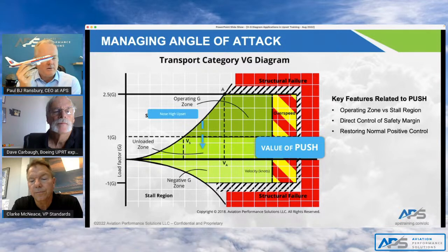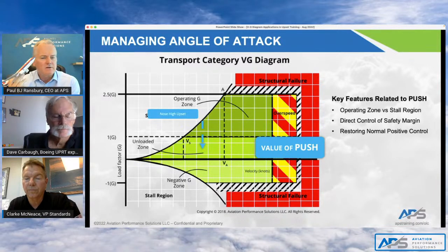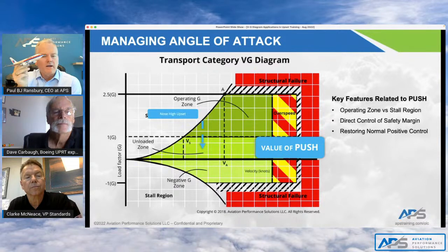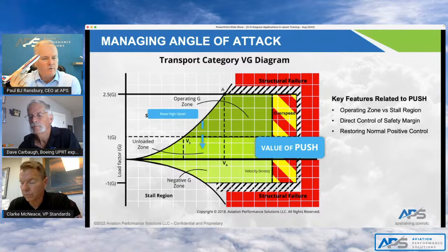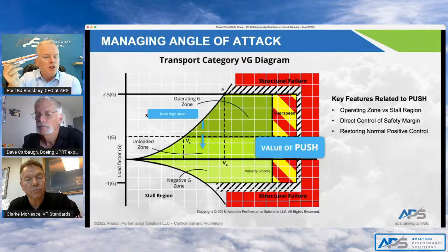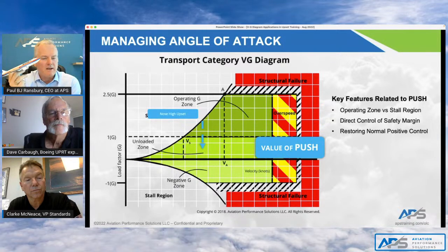Depending on the airplane and the technique recommended by the OEM, it may be a complete straight wings level push, or in certain situations, you may have to unload all the way full forward and then actually roll the airplane to help roll that lift vector off to get the nose coming down. It's not uncommon in these scenarios, especially anything 30 or 40 degrees nose up, to be over the top below the 1G stall speed, but there's no reason for the pilot not to be in full control. They have to push and unload below 1G, which is a great example of why, in your mind as a pilot in an upset, including a nose high unstalled upset, the focus is managing angle of attack. Even though you're not stalled, you're mitigating the threat, which is the upcoming stall if you don't manage angle of attack effectively.